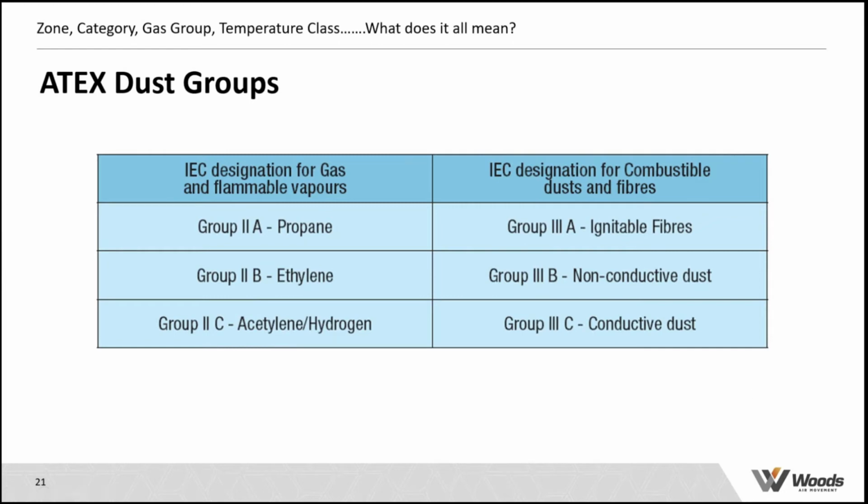So if you think about it, if you've got any metal filings, if you've got carbon, anything that will allow an electrical signal to be transmitted inside the motor along the shaft through the seals, etc. So that's the way that is. So very important. So you'd have, by example, cotton. You'd have things like sugar, flour, paper, wood in the non-conductive ones. But things, as I said, metal dust, aluminium, zinc, carbon would all fall into that category. So the people need to understand how the thing is going to be used.